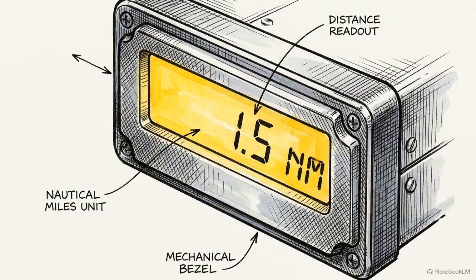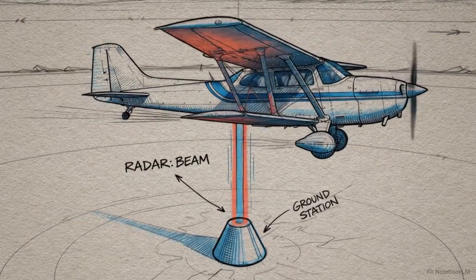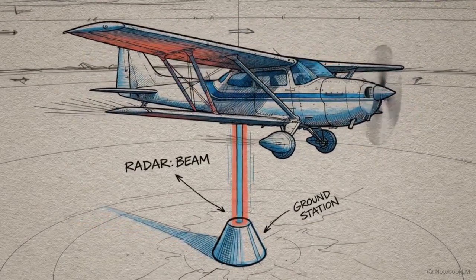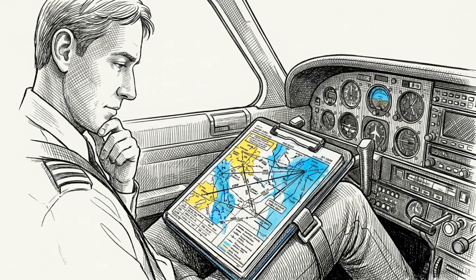The cockpit display will indicate 1.5 nautical miles. The radar correctly measures the 9,000 vertical feet of air separating the antennas and converts it into miles, equating roughly 6,000 feet per mile. Aviators rely on a standard operational rule to identify when this slant error becomes mathematically negligible.